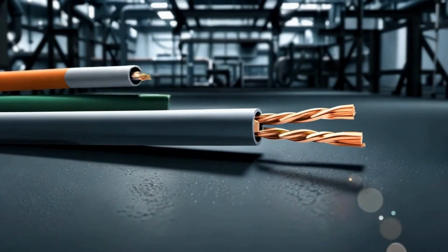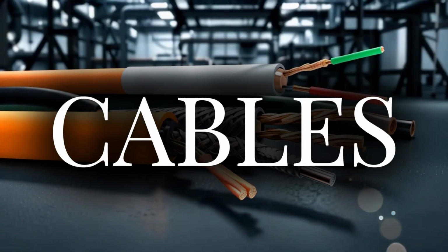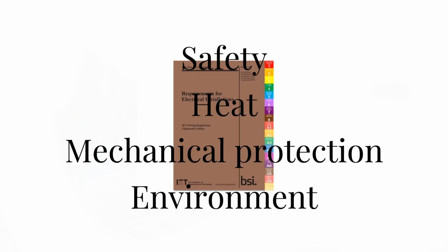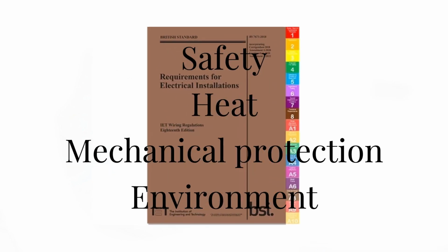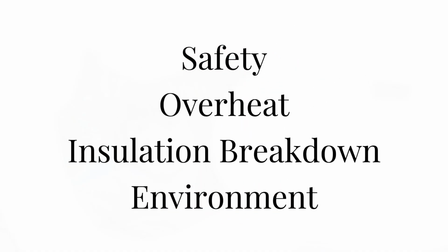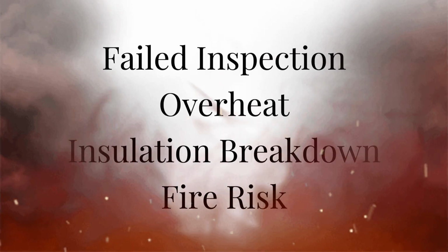Let's talk about something that seems simple, but actually isn't. Cables. Because choosing the right cable isn't just about what fits or what you've seen before. It's about safety. It's about heat. It's about mechanical protection. It's about environment. And it's about complying with BS 7671, the wiring regulations. Get it wrong and you're looking at overheating, insulation breakdown, failed inspections, or worse, fire risk.